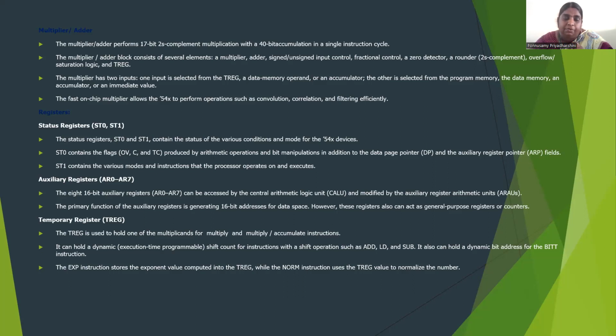Next, the types of registers: status register, auxiliary register, and temporary register. The status registers are represented as ST0 and ST1, and contain the status of the various conditions of that device, whether that is regarding the flags, such as overflow, produced by the arithmetic operations and bit manipulations. And ST1 contains the various modes and instructions.